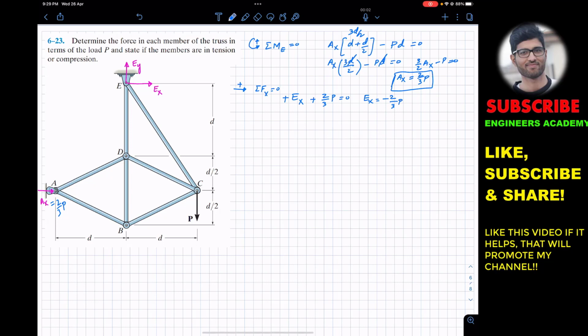2 divided by 3 P. And we can say that EX magnitude is 2 divided by 3 P, and it is actually acting towards the left. So this means that the assumed direction of EX is not right. EX is actually acting towards the left. So let me draw that EX towards the left. So this is that EX, and when it is acting towards the left, its magnitude is 2 divided by 3 P.